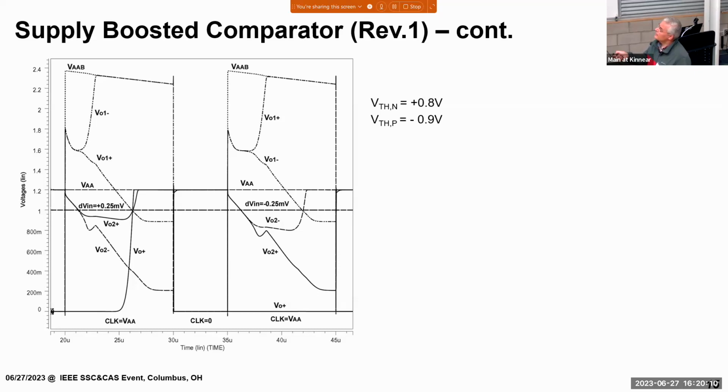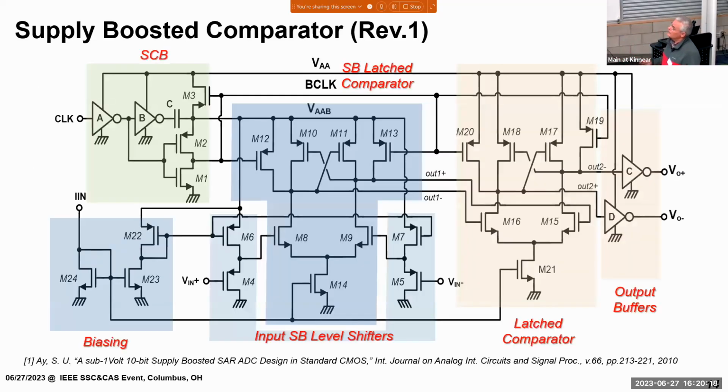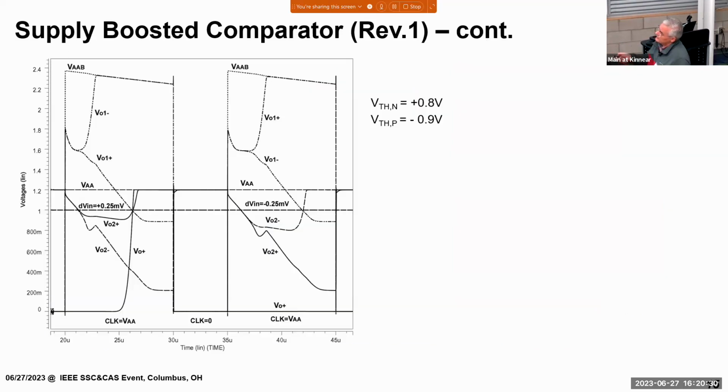Okay, and your switches follow the same thing, although their impedances are changing. It's not going to affect the final decision because of that positive feedback that you have. The only problem here is this loading effect that slows it down. This can go much faster and start making the decision. That's why in the second one, we reduce this decision point to where the supply voltage is still sufficient.